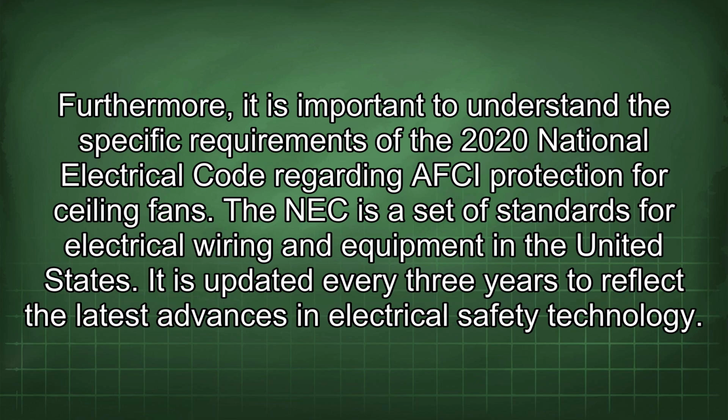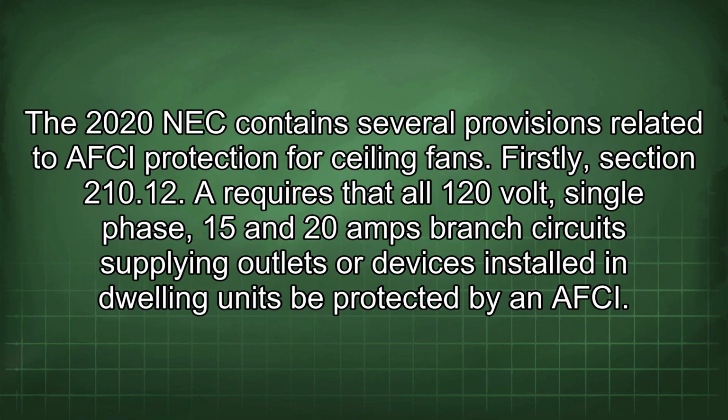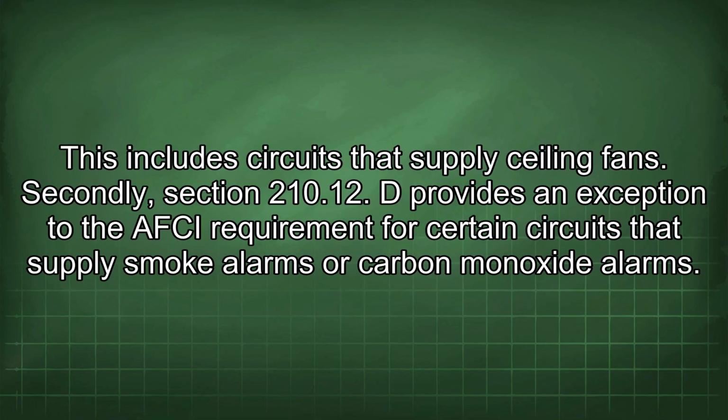It is updated every 3 years to reflect the latest advances in electrical safety technology. The 2020 NEC contains several provisions related to AFCI protection for ceiling fans. Firstly, Section 210.12 requires that all 120-volt, single-phase, 15 and 20 amp branch circuits supplying outlets or devices installed in dwelling units be protected by an AFCI. This includes circuits that supply ceiling fans.